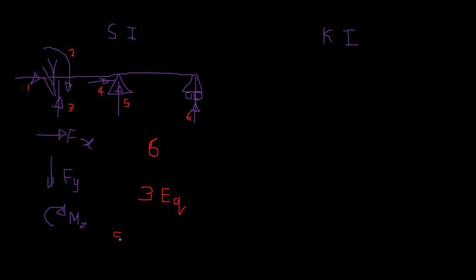So your statical indeterminacy becomes 6 minus 3 equals 3. So you need an additional three equations to solve this structure.